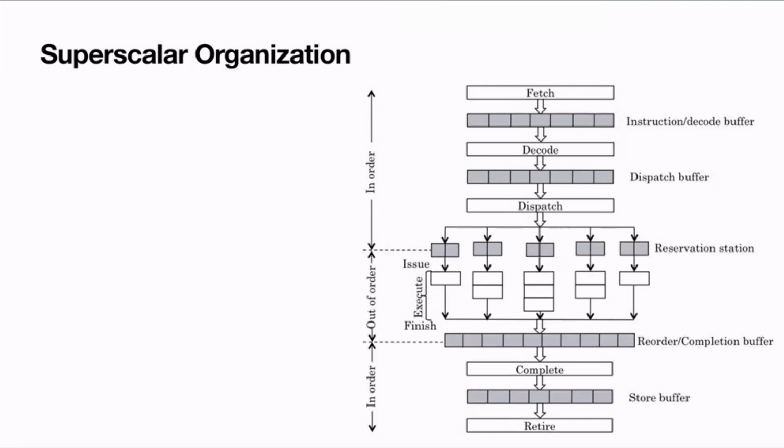And then at the time of committing, we again come back to the reorder buffer, and because the reorder buffer is working like a first in first out queue type of design, that is going to ensure the ordering and so on. So superscalar processor means automatically out of order execution has to be there.